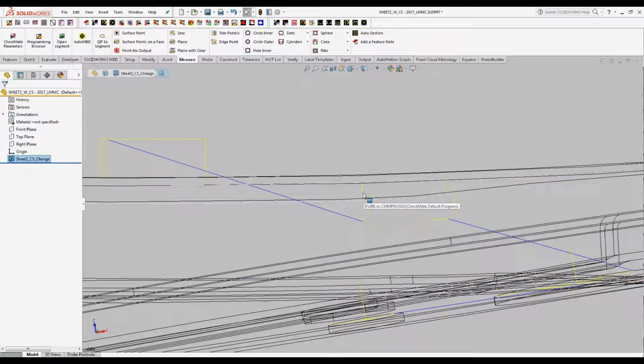It's perfect. Now this other one over here on the right-hand side is the same as that large circle measurement we just dealt with. Even if I flip it and have the vectors going the other direction, it's still touching down on the bottom material thickness of the part, and I don't want that. So I need to flip it, and then I need it to go up the material thickness. I could use the / key to flip it, and then use the plus key in a second step to move it up the material thickness, or I can do it all in one step, like I said, with the asterisk key. If I hold the asterisk down and now click it, you can see it's flipped and gone up the material thickness.